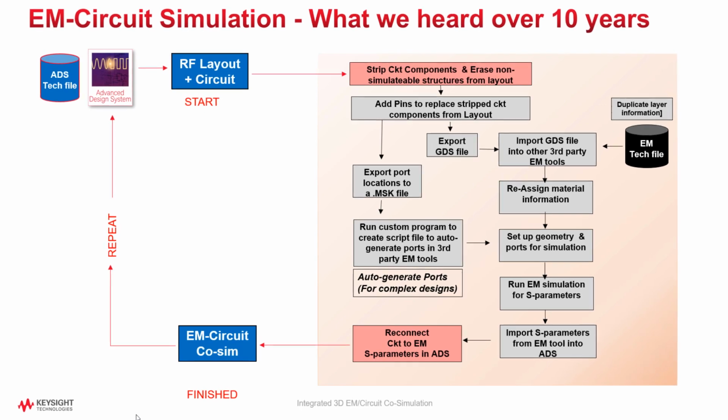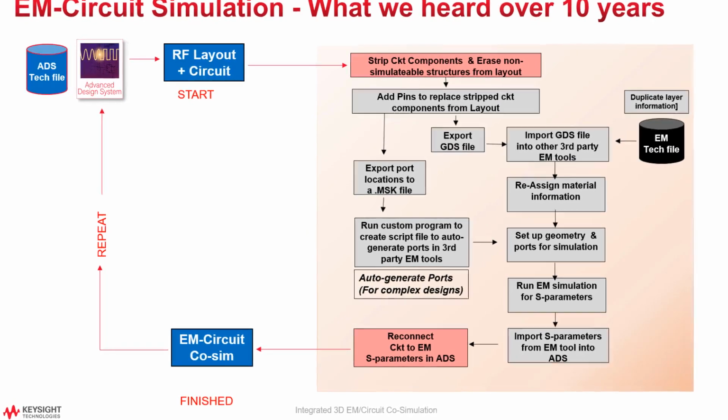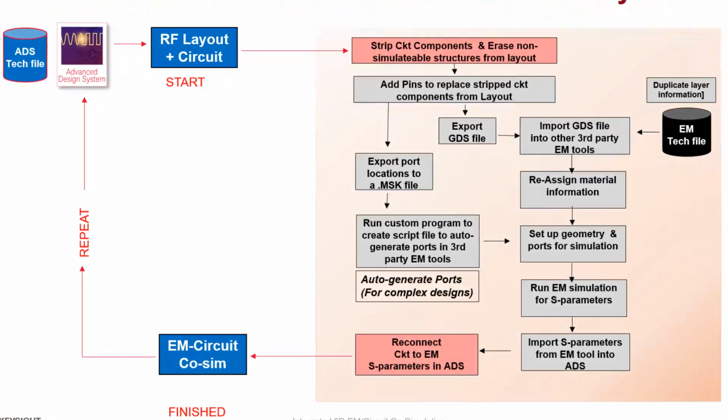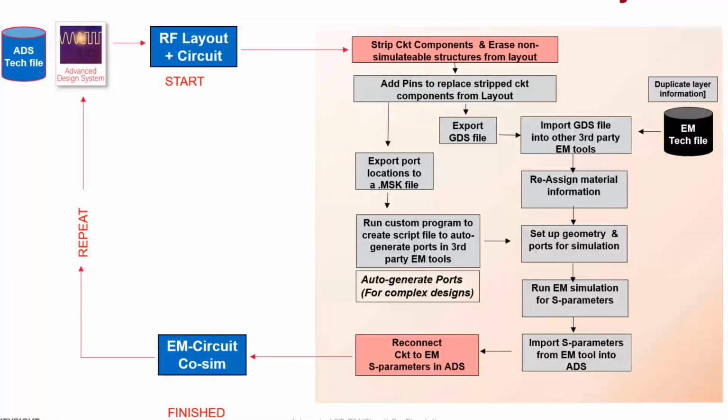For example, and most of you might have experienced this flow, first, the design is exported to some EM simulation tool. All SMD components and active devices are stripped off and removed from the layout, and the remaining portion to be simulated must be cookie cut out to be analyzed by the EM simulator.